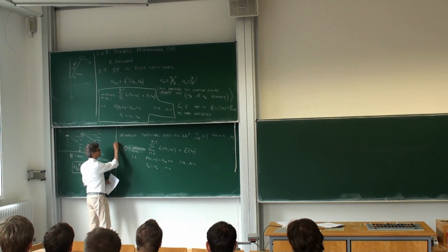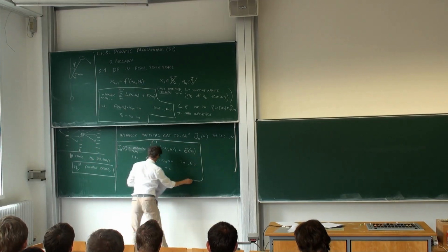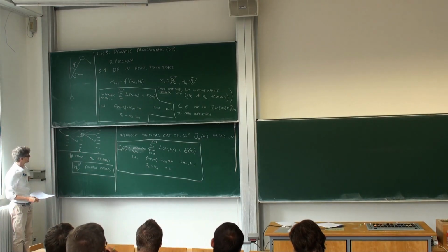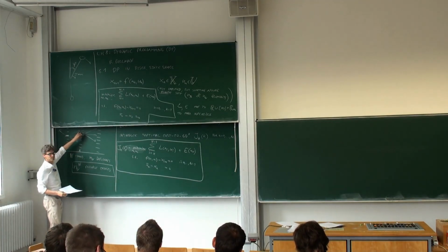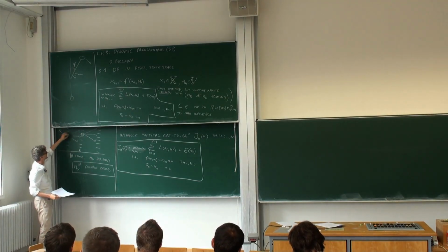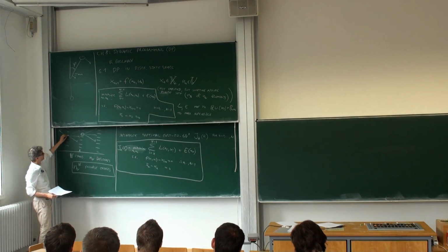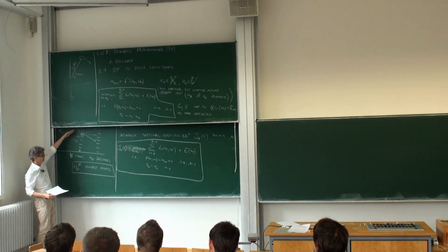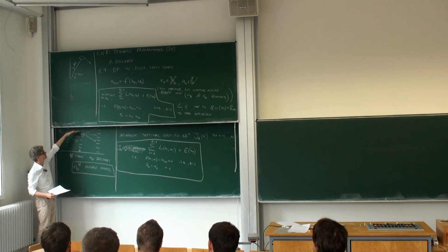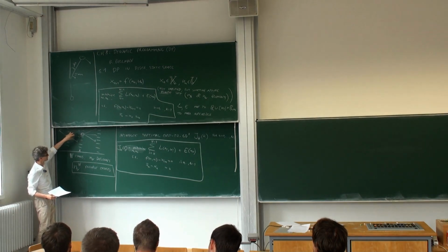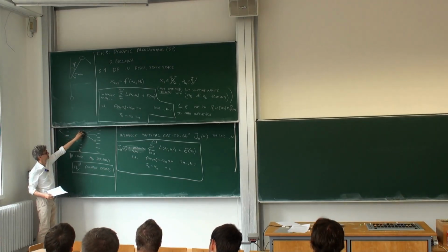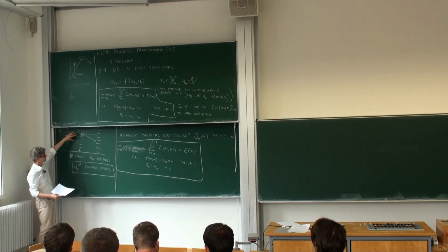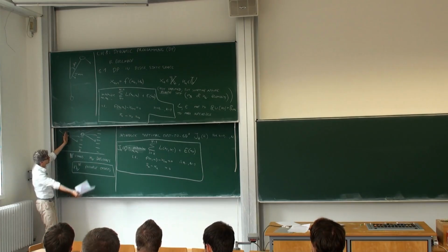Okay, so that's the definition of the cost to go. You might say nothing is gained, hey, how can I solve this problem now? Does it help me? And it does help us, because if you would know this cost to go, and you are faced with a decision, from any state where you are now, what would be the optimal action for the future, you would just look at all your N_u possibilities, and from those you compute the cost that this one stage plus the cost to go gives, because then you know that will be the optimal, and you choose the best of them, because that will give you the optimal way.